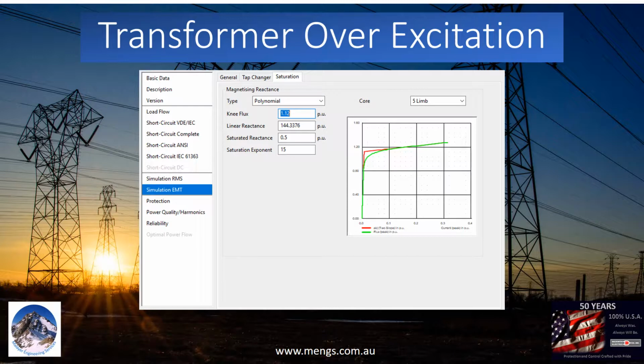When the voltage across the magnetizing branch is higher than the knee point, its impedance drops to a very low value and it will increase the magnetizing current. The transformer differential relay will neglect magnetizing current as it is a very small value in normal operation. But during overexcitation, this value is not negligible and can push the relay to trip during a transient overexcitation.